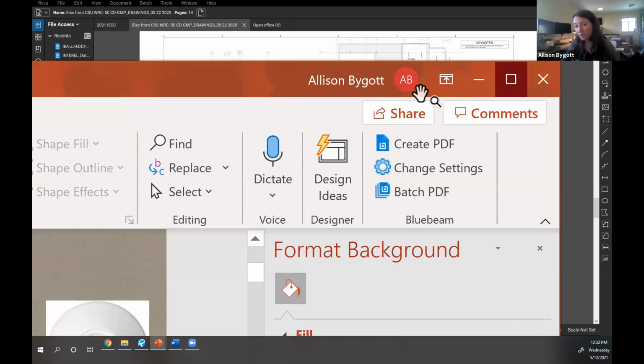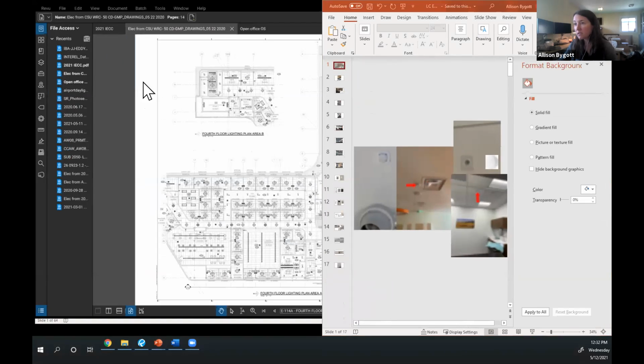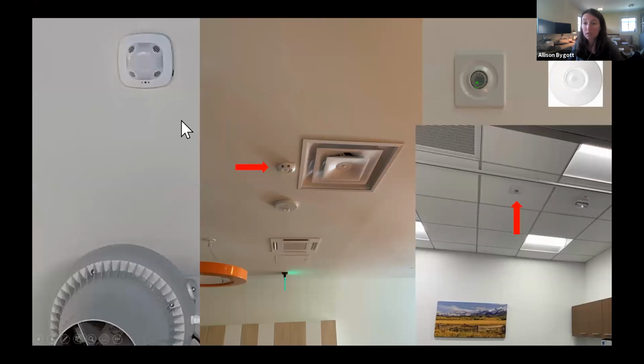So after a design review, we go test in the field and see if the installation meets what was included in the contract documents. And sometimes I wind up in a tough situation. Sometimes I do have scope to do a design review. Sometimes I don't. If I get asked to do just code required commissioning, I don't get a design review. And if I don't get a design review, I can't verify that the design actually meets code. If it doesn't meet code, I might be commissioning to the contract documents, not what's actually required to be installed.